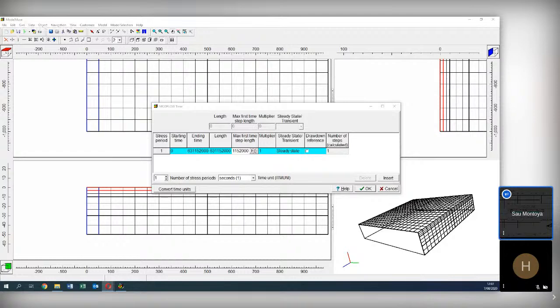For example, in our pumping test, the first day we can select to be modeled every hour, so we define 24 time steps. In this case, we have 20 years, but the whole 20 years will be defined as just one time step. Okay? This is for this exercise.